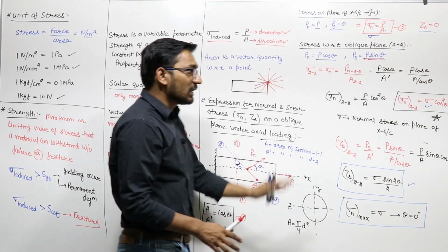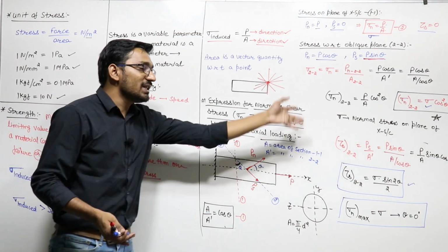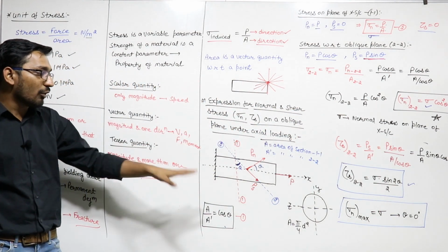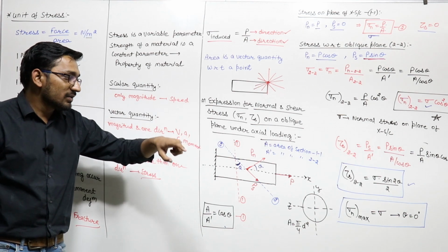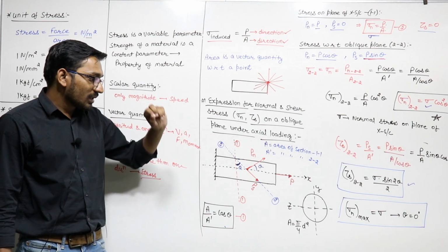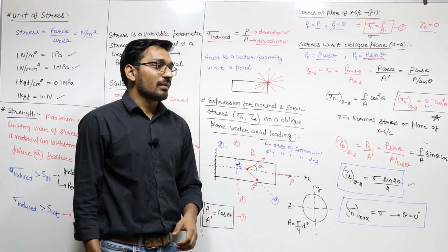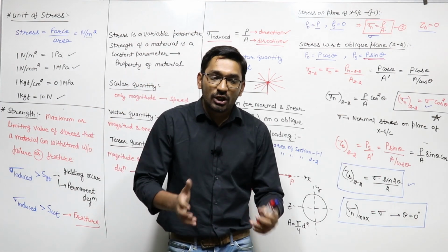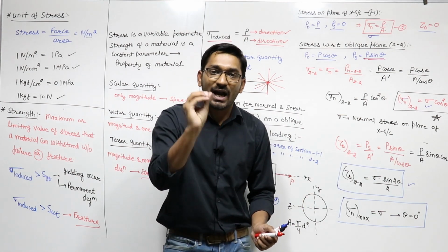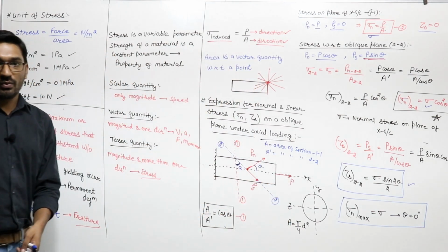So the first conclusion from this derivation is that, we will also see this in your combined stresses and strains or your Mohr circle, but right now for the uniaxial case, sigma is maximum at the plane of cross section, or in any member normal stress is maximum at that point or at that plane where shear stress is 0.